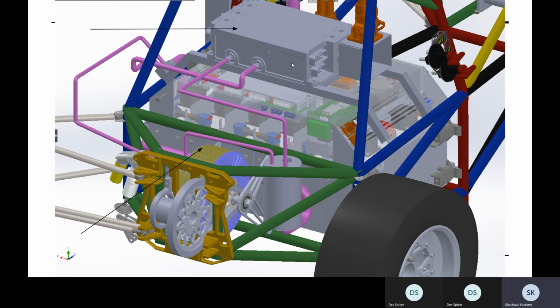The motor and inverter are on a liquid cooling circuit in parallel, meaning that the fluid doesn't flow into the inverter, out of the inverter, into the motor, out of the motor. There's a branch in the cooling conduit so that you're not co-heating the motor with the inverter. Does that make any sense? Yeah. So we have a cooling system. This is a reservoir here for it. The CAD model is kind of rough, but it's come along since, for sure. I've seen a better model of this in the KS2E assembly.